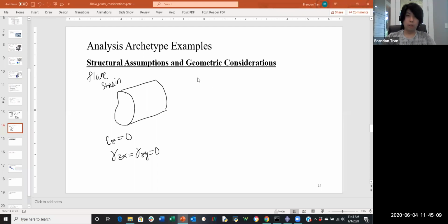So that's plane strain. Another simplification is plane stress, where you assume that whatever substance you're dealing with is not that thick. It's actually very thin. So stress doesn't matter in this direction because there's really no material. If any out of plane force is applied to this thing, it'll basically break. I kind of made this thing just look like a sausage, whatever.